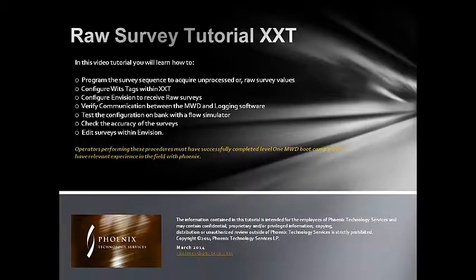In this video tutorial, you'll learn how to program the survey sequence to acquire unprocessed or raw survey values, configure WITS tags, configure Envision to receive raw surveys, verify communication between the MWD and logging software, test the configuration on bank with the flow simulator, check for accuracy of the surveys, and edit surveys within Envision.